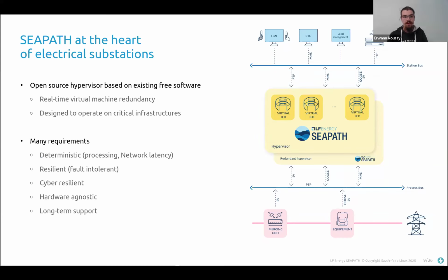So here we are. That's the SEAPATH project. SEAPATH is really at the heart of the electrical substation. On the right you have a basic schema of an electrical substation from an IEC 61850 point of view, with the process bus and the station bus. The equipment at the bottom of the schema directly sends information to virtual IEDs, so IEDs running inside virtual machines. And those IEDs are connected to the management, the HMI, and maybe a SCADA or any of these topics.